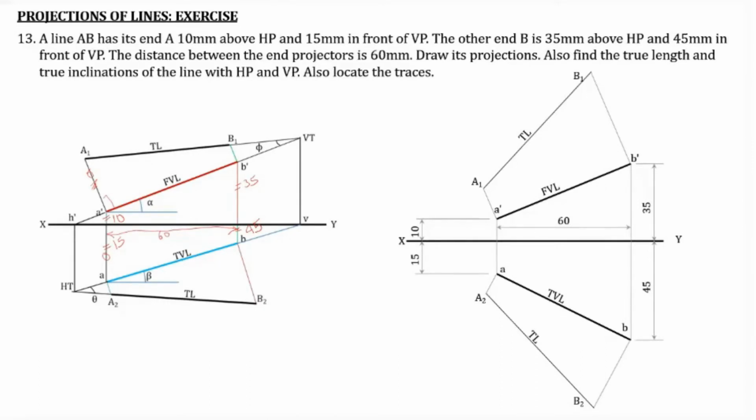A slight variation of 1 millimeter or 2 millimeter is also acceptable, but more than that, that is a 5 millimeter difference, cannot be accepted. So this is the simple procedure by which you draw only perpendicular lines to the front view as well as the top view in order to obtain the true length lines.